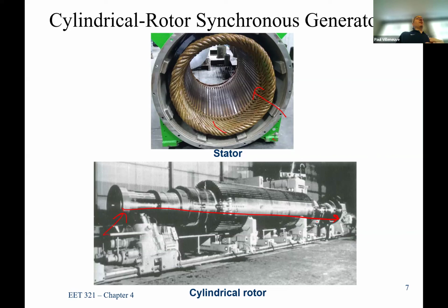That's why they do have something called vertical axis wind turbines. With that same concept, they're thinking, oh well, we'll put all the weight at the bottom, and then we won't have all the weight at the top of the tower. The problem is that weight is all sitting on that bearing, and you need a really heavy duty bearing to do that, needing a lot of maintenance. So from a mechanical perspective, it's not practical.